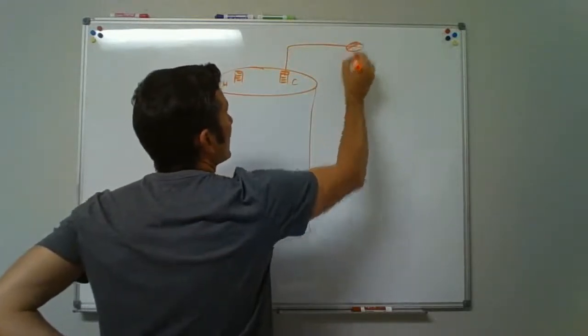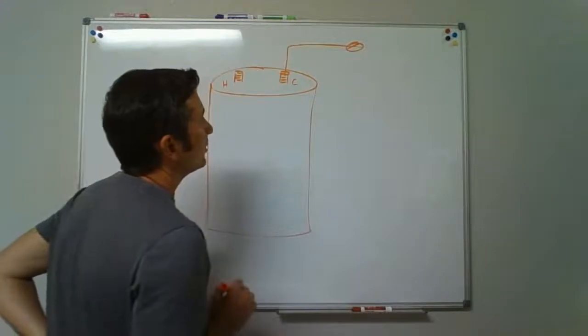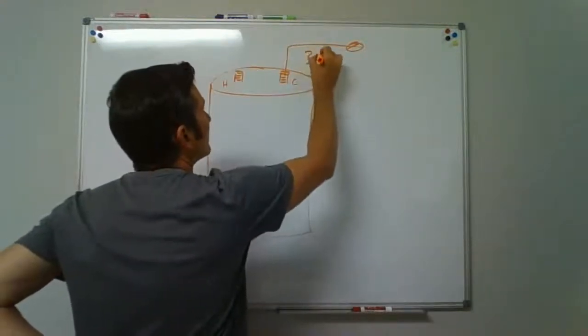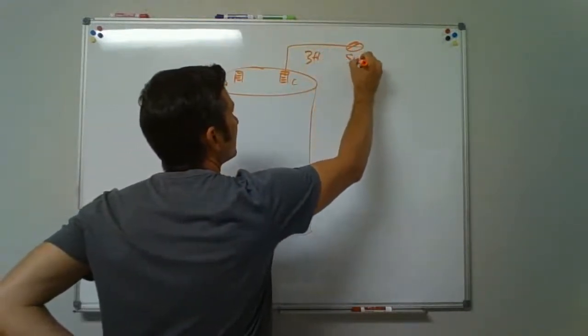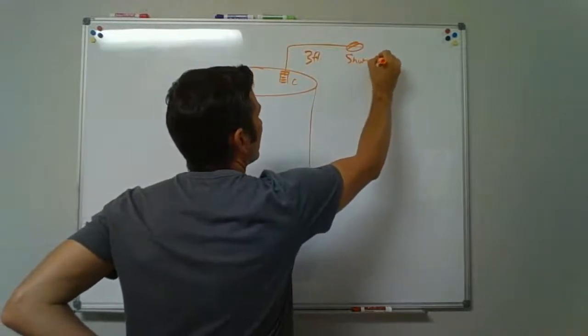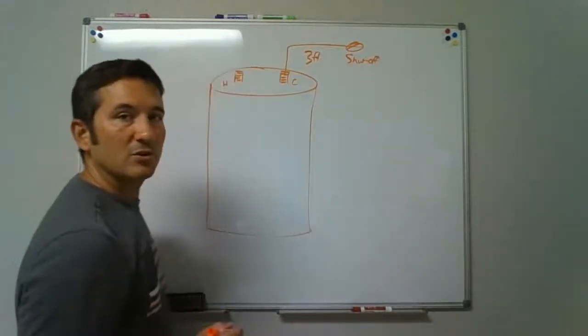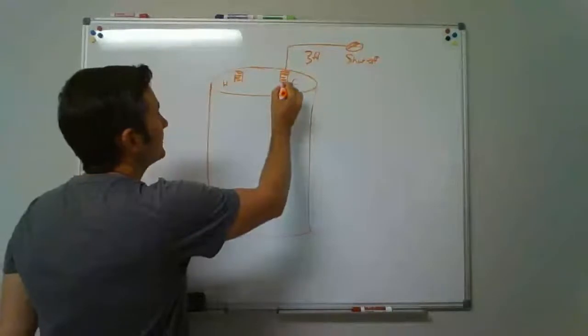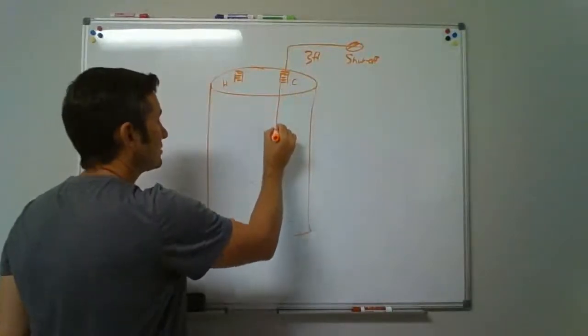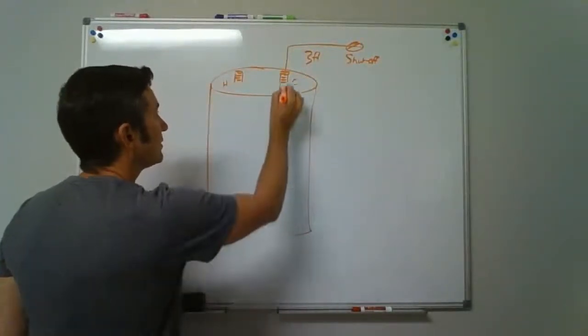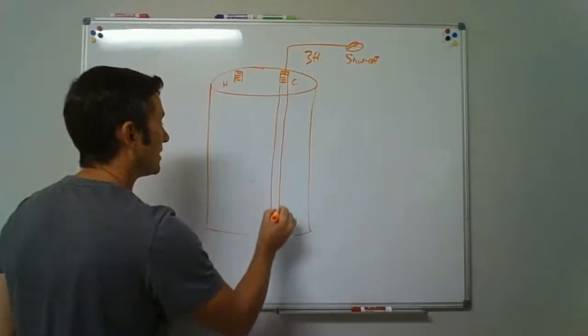We just read that you've got to have a shutoff valve within 3 feet of the water heater. Within 3 feet, you've got a shutoff there. But the cold just dumps in the top. It's got a tube that attaches to this that you can't see, and it runs right down close to the bottom of the tank.